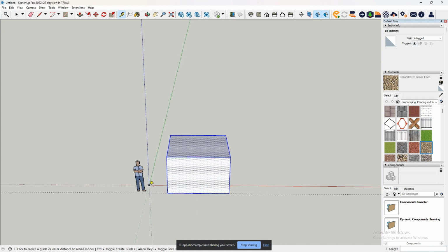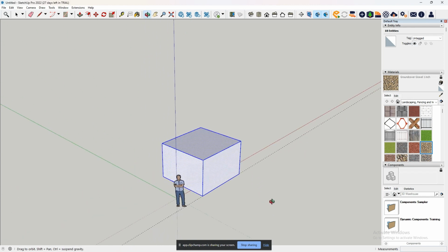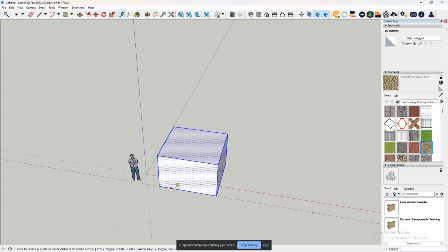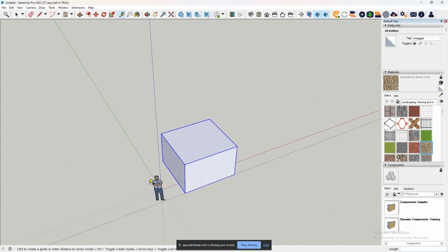Now, as you could just see that I just did accidentally, is very much another part of the tool: the fact that it can create these guidelines here. These guidelines are very useful for trying to lock on different parts of your model. It's as simple as, if I wanted to create a guideline going this way, you would want to find a part on your model that has a similar angled line to it. Don't click on the midpoint, but click on anywhere else where it says on edge, and you can either double click it to get a line on the line that you've already selected, or click it once and then start dragging it to wherever you want.